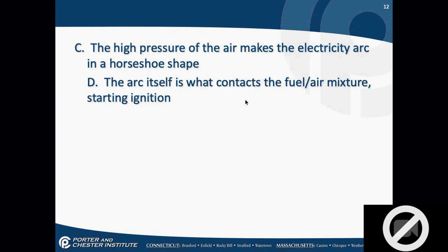Okay, once I have fire, I don't need to maintain that ignition as long as I still have flame. So once I have flame, I can shut off my ignition, and I can continue to throw oil into the fire. As long as combustion is maintained in the combustion chamber, I can continue my combustion process, because the heat from the combustion itself will ignite the new fuel.